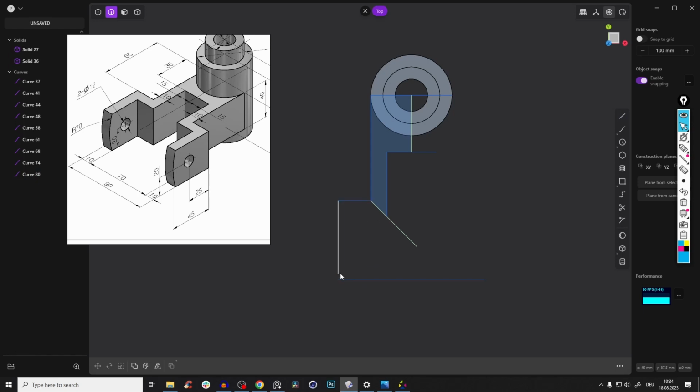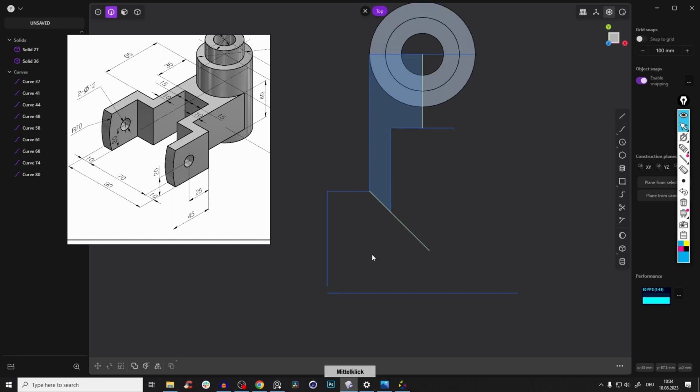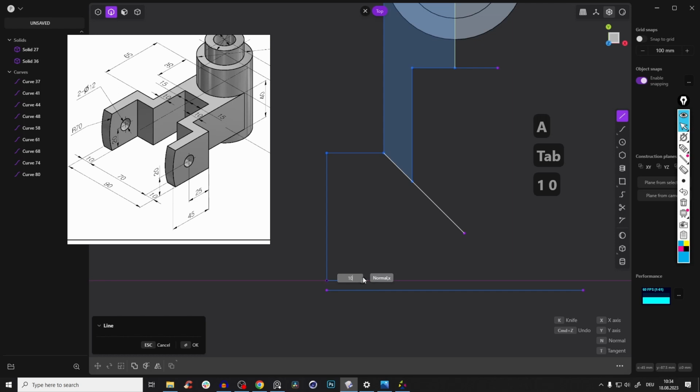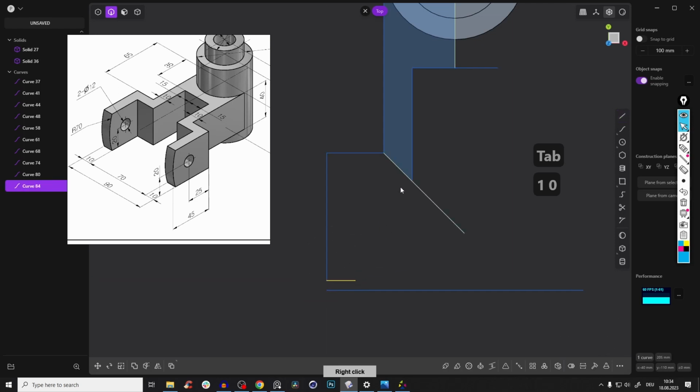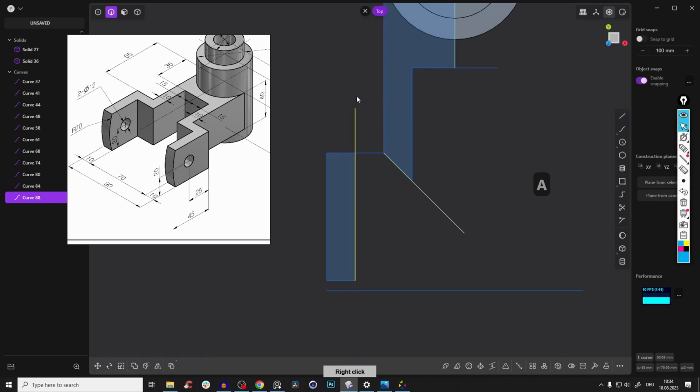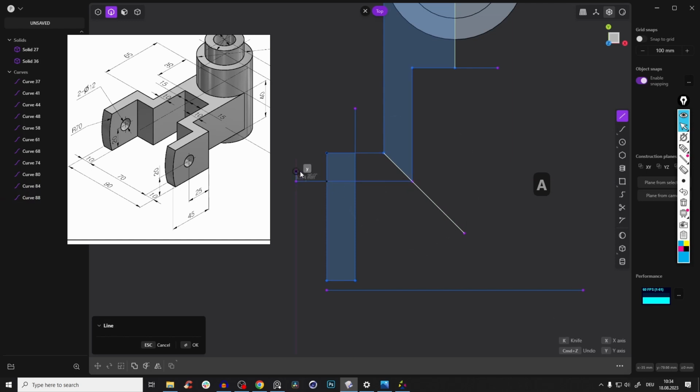And now what we can do is give it again a 10 millimeter thickness. And here we know how long those lines will be, because we can again just give a 45 degree angle. So let's do it differently this time, just to show you some techniques. So Shift A, and let's first of all create here a 10 millimeter thickness. So this is fine. And now we have to meet somewhere at this intersection. So very simple, just create the line and drag that somewhere completely out. We will trim that. So just to show you, create a new line with Shift A and just go here.